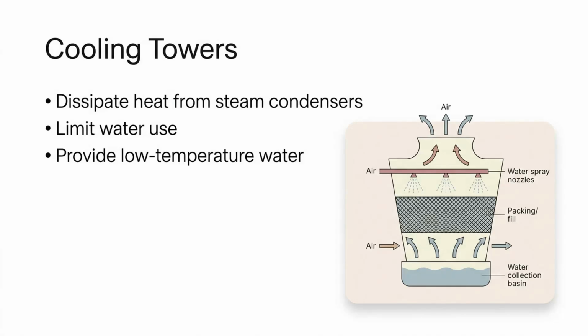Cooling towers are specialized direct contact exchangers. They dissipate heat, conserve water, and supply low-temperature cooling water to maintain a plant's thermal efficiency. They do this by spraying warm water over a wide surface area while air flows through it, causing evaporation.